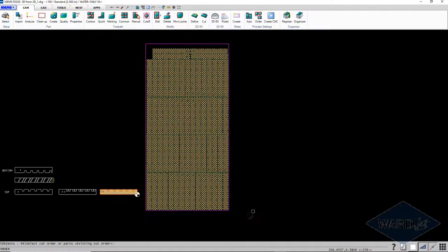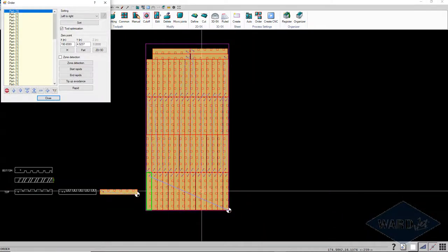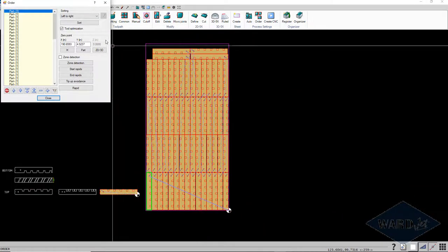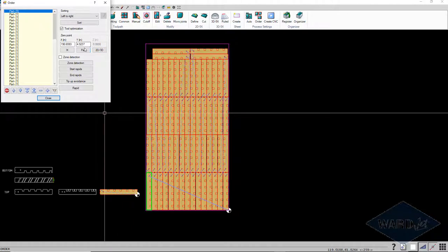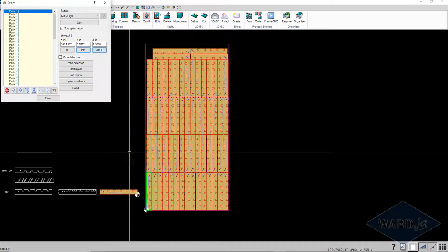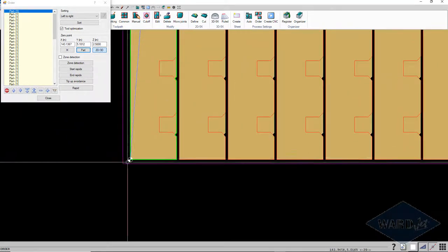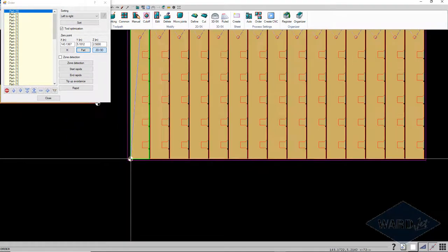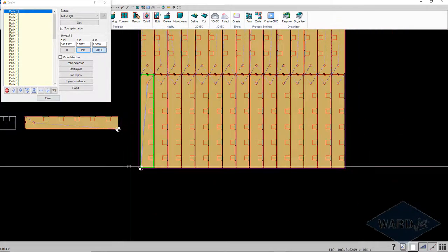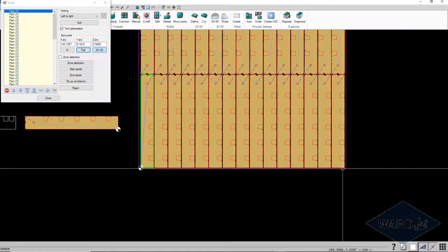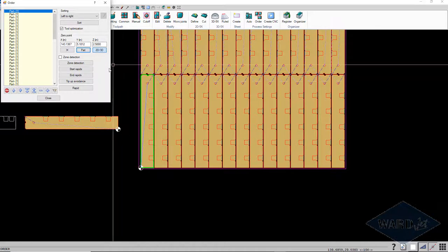And then this is always a thing to remember with parts that come from the 3D 5-axis world: we want this Z to be equal to our material thickness. When we're doing the single part, I showed you just to click on the part and the Z goes to that 2.5, but in this case when you do that on a nest, it also moves it to the corner of the first part where we had the 0 point set, which we don't want. We'd want that more at the corner of the sheet.